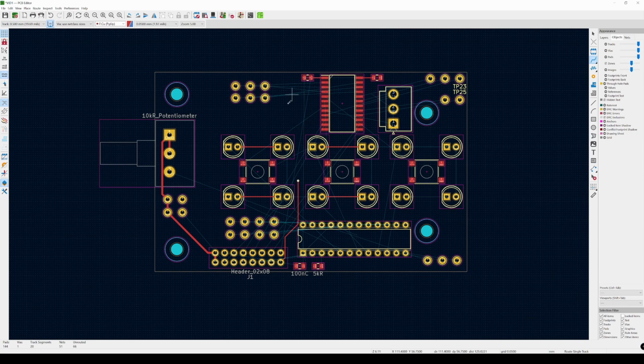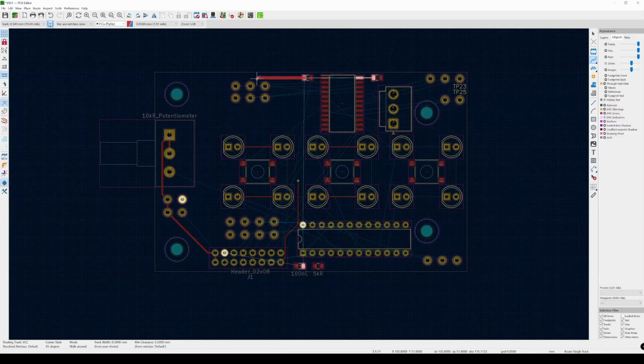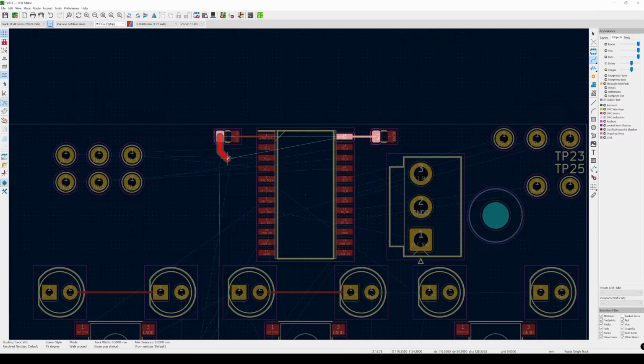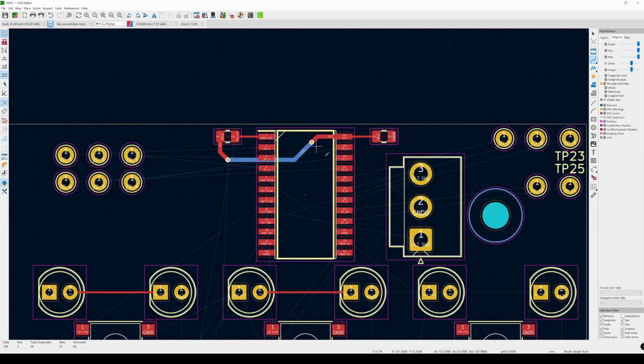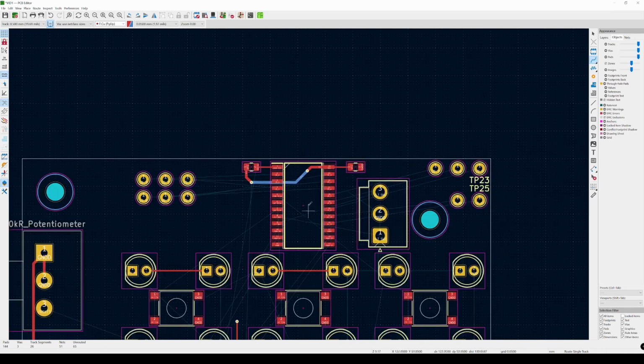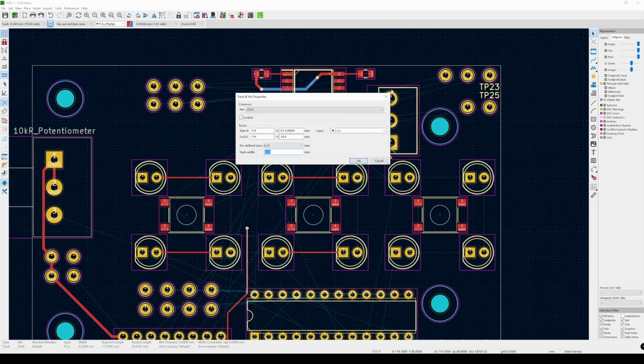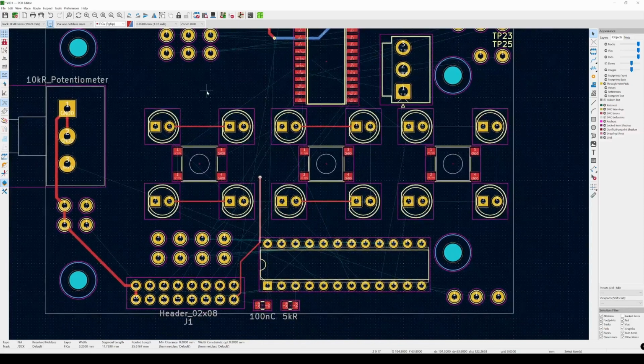And sometimes you just have to do some really stupid wiring, like here I have to connect here, so you just might have to go around all the way here and create something weird like this, since there's no other way. Although here, what I would do is put a wire, go underneath, and turn up here, and now we have our VCC connected there. Just remember, utilize your wires, go underneath things, use all the space that's available, use thinner tracks if you need to, and try to find the optimal way.